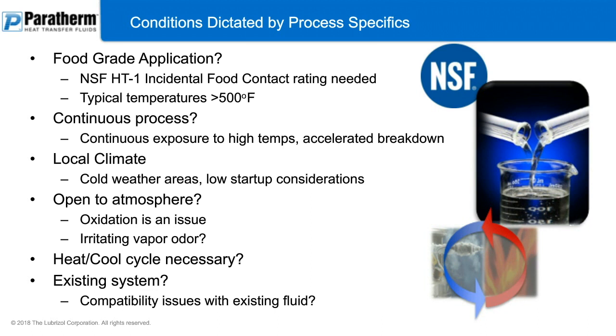Under those circumstances, you're going to have compatibility issues with the leftover degradation products, carbon sludge, and carbon buildup. But you also want to make sure that whatever existing fluid was in there is compatible with the new fluid that you're choosing to put in. So two considerations and two selection processes from that point. One, should I be choosing a fluid that has the same chemistry and compatibility as the fluid that was in there previously? Or if you're not going to do that and you're choosing to go to a different fluid for whatever reason, you need to make sure that you're taking the proper cleaning steps to get that fluid out of the system so it doesn't contaminate the new fluid.